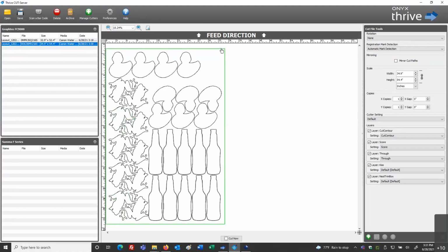That feature was created out of a customer request, which is very nice, and also has been enhanced upon now with the offset information. So we can offset that out to our amount that we desire. And that's going to be, in this case, 1 inch away, but that is automatically going to be a cut path. You'll see over here that's set for nest trim box. And that information then could help facilitate for weed bordering.